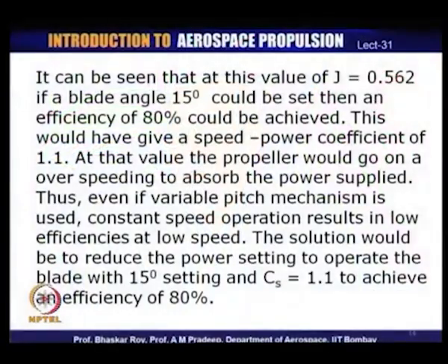So, the result is under certain operating condition, as we see, it will be more judicious to go for a speed control, the speed at a lower speed of operation, and then choose a propeller blade setting, which now as we see can be a fine setting, at which you get a good efficiency, 80% efficiency of operation of the propeller.